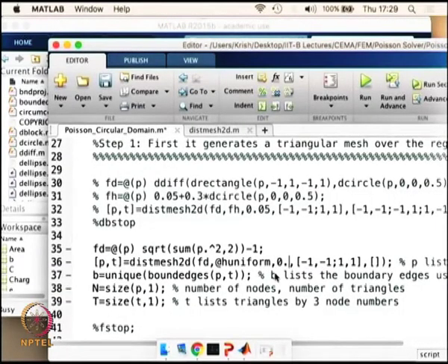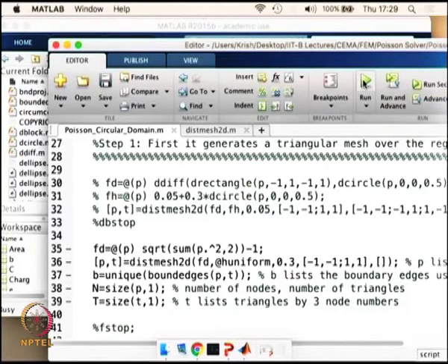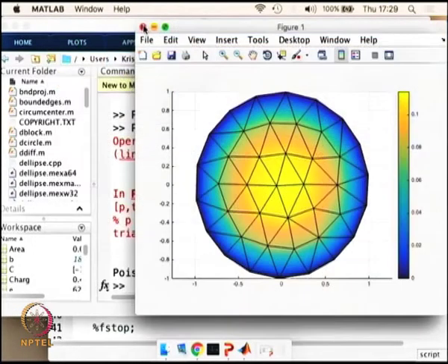So let's go to 0.3. So the maximum edge length is going to be 0.3 now, and I'm running the same program. So you see the value is getting more and more finer. You see the nuances of the equipotential areas. Initially when we had 0.5, we didn't really see the green equipotential line. We start to see it now.